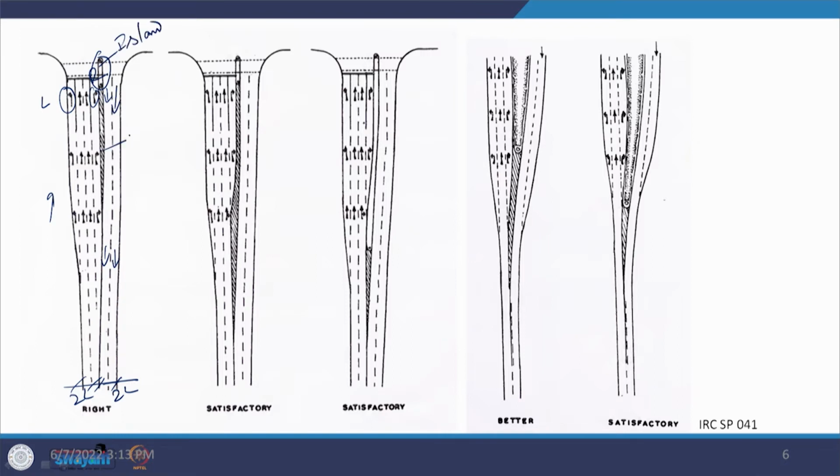and there are pavement markings being placed on this side. So, that is how the segregations have been achieved, all rest of the markings remain the same. So, what we need to do is a flaring of this particular section at this point from a 2 lane to something like a 6 lane system. Now, if this type of design is being provided, it is quite a good design.